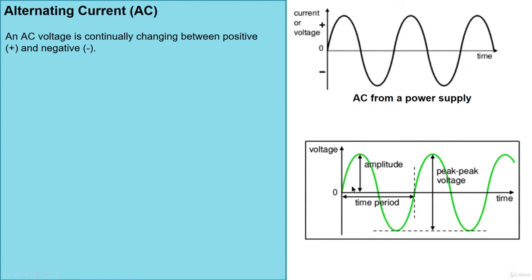This voltage time graph shows various properties of an electrical signal. In addition to the properties labeled on the graph, there is frequency, which is the number of cycles per second. So this diagram shows a sine wave, but the properties apply to any signal with a constantly repeating shape. The first property of an AC signal is its amplitude, which is the maximum voltage reached by a signal. I guess you know the amplitude of the voltage is measured in volts.